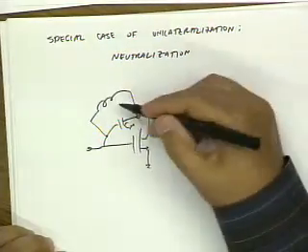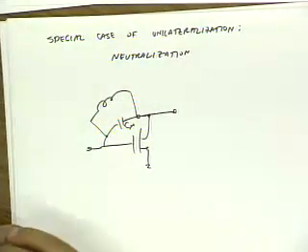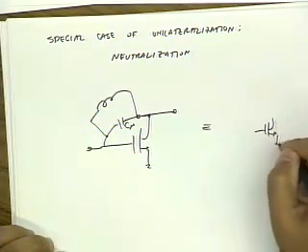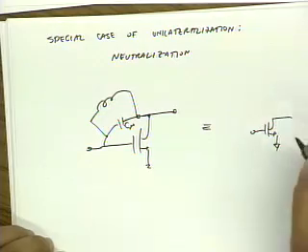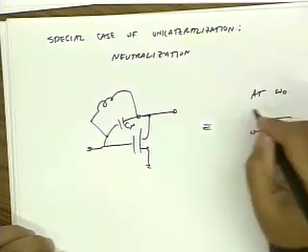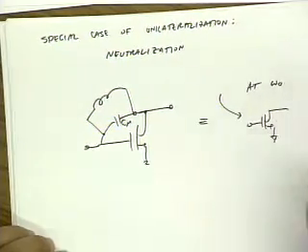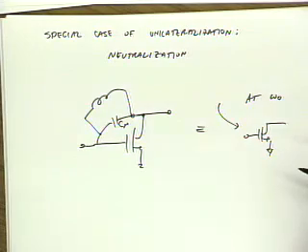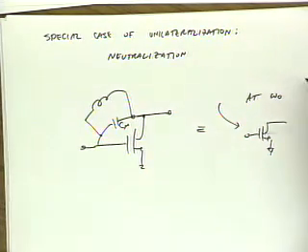At a single frequency, this inductor cancels out this capacitor, and the net effect is a unilateral transistor. So at one frequency, I've gotten rid of C mu. And that's very easy to do. Turns out that if you do that, you actually do get more gain out of your device. You can get a lot more gain out of your device. And yes, there's a question?